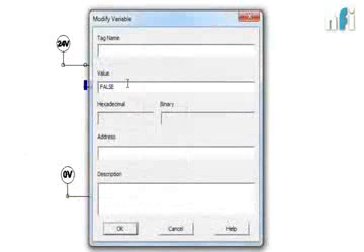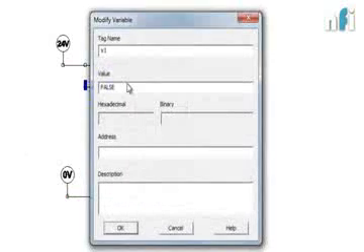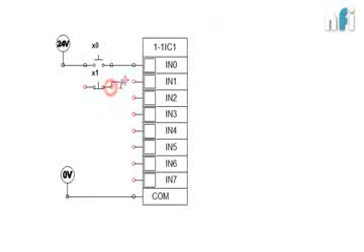This is my normally close button. As its symbol indicates, it is passing the signal in normal position. That is why it is called normally close, because the switch is closed normally. When I press this button, it will be open, and it is again spring loaded. When I release this button, it will be closed again.